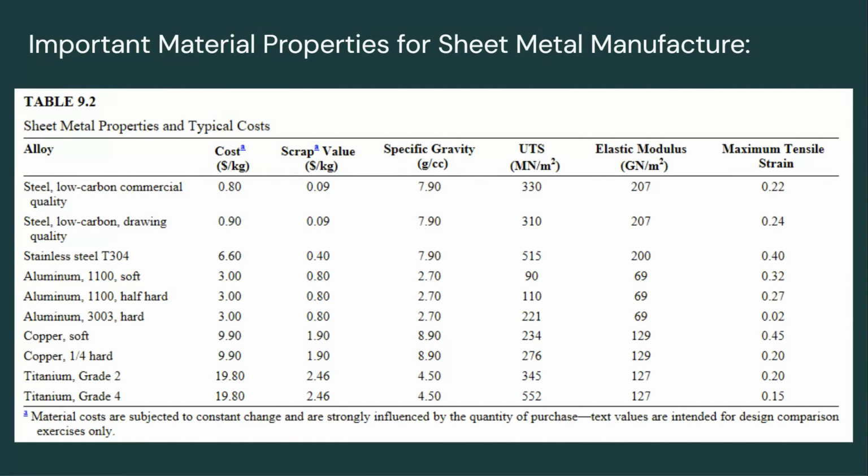And aluminum and titanium both outshine in terms of density, but for most applications, steel is going to be the material of choice, especially if you think about car and automotive processes or enclosures like computer cases and whatnot. The aluminum and titanium really get used more where strength-to-weight ratio is important, and you start thinking about aircraft or spacecraft, where the costs are worth it. But otherwise, you'll see a lot of steel used in sheet metal manufacture.